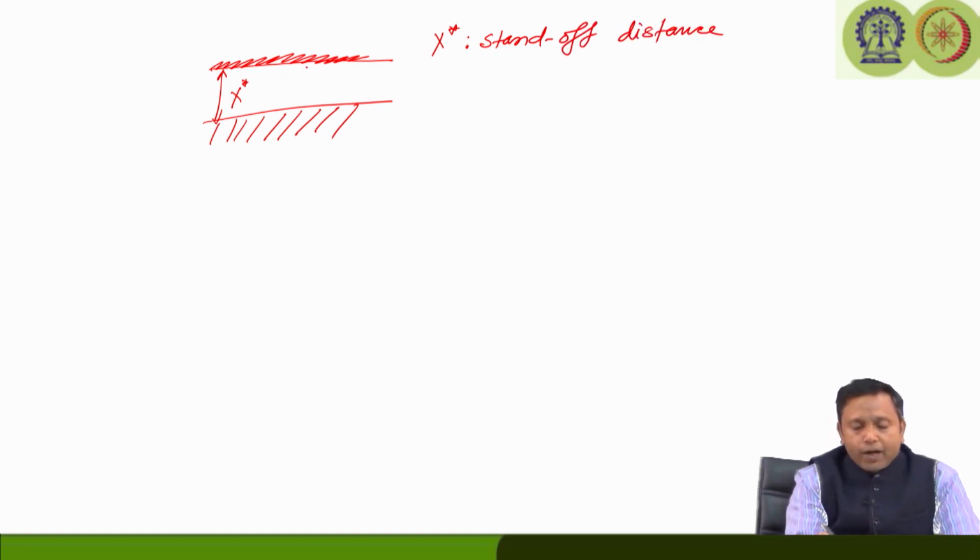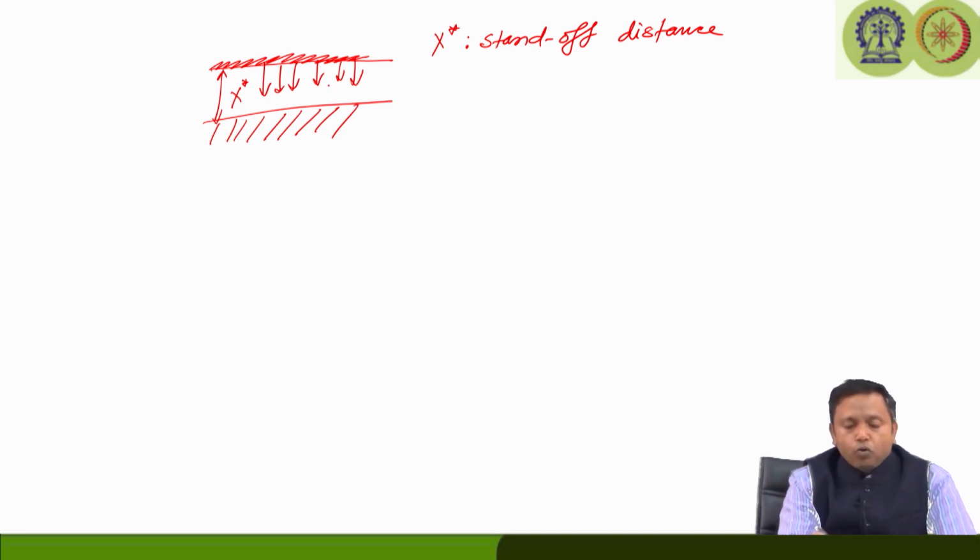Now, this flame is going to provide the heat for further decomposition of the ammonium perchlorate crystals and the pyrolysis of the fuel binder. So, what it is essentially doing is providing heat to the propellant surface for further reactions. What we need to equate is that the amount of heat coming from the flame is going to be used for heating of the propellant as well as the pyrolysis of the fuel binder. Heating of the propellant means there will be some initial temperature of the propellant that goes to some surface temperature of the propellant Ts, and once the reactions occur it will reach a flame temperature.